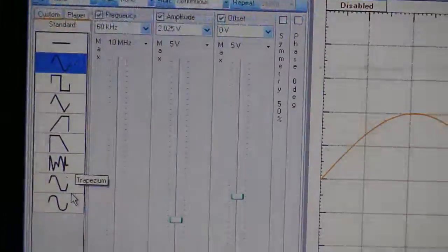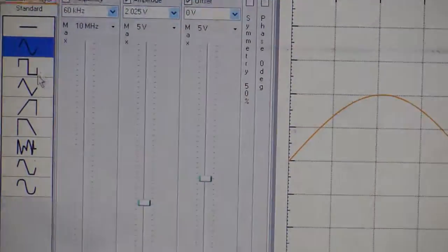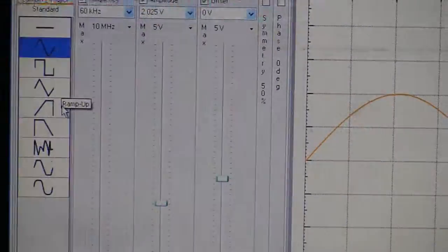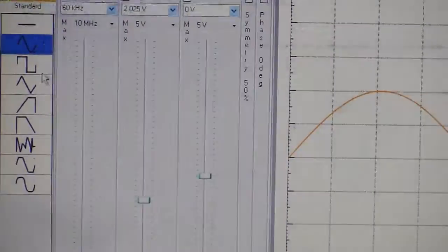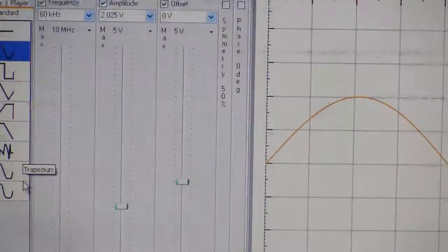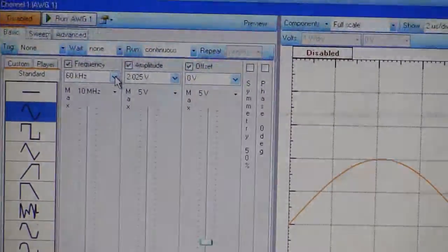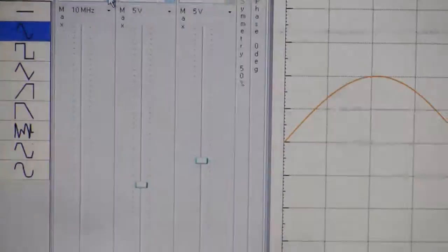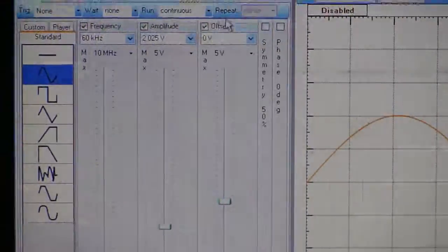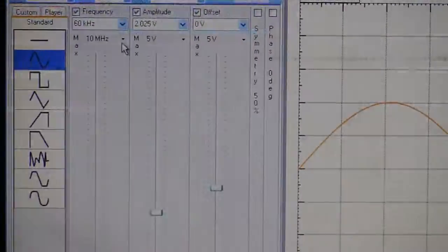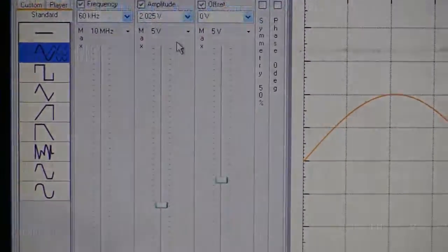The Waveform software, which offers you the waveform generator feature, gives you an option of generating even aperiodic signals, which can be a combination of any of these signals which are prescribed over here. At the same time, the periodic or aperiodic signal which you want to control with parameters such as frequency, amplitude, and offset can be controlled with the help of this graphical user interface with ease.